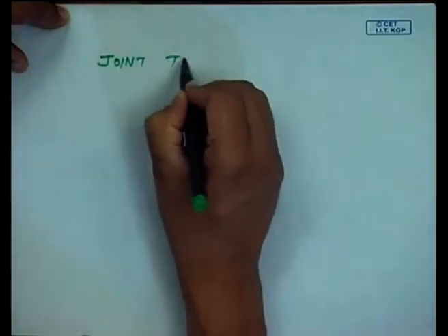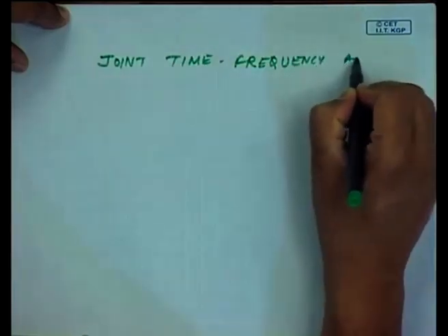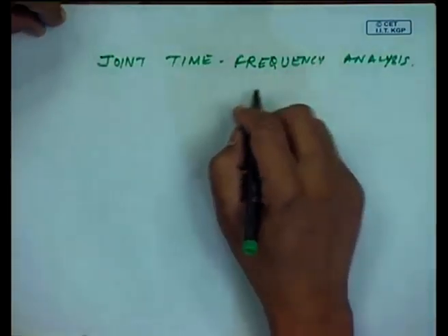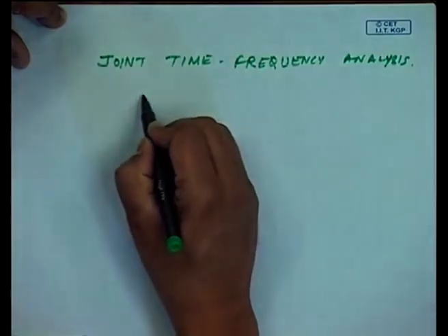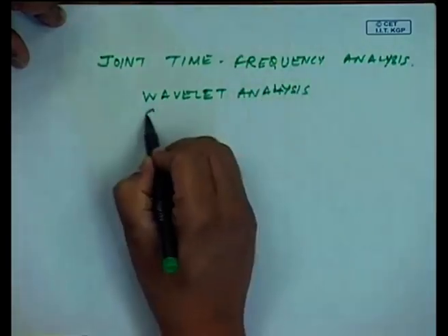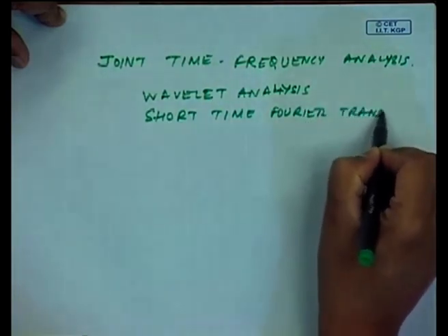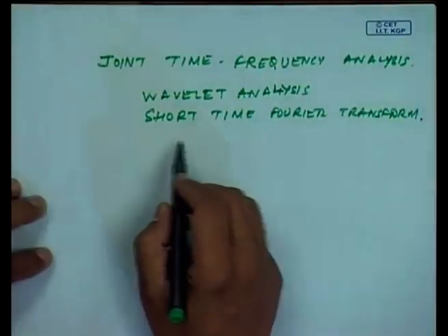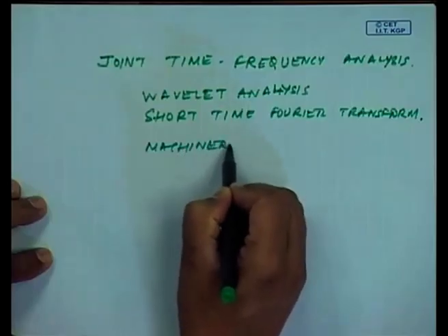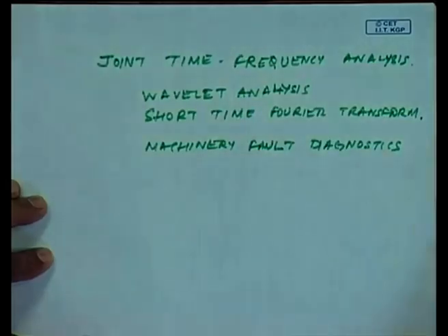But this has given way to nowadays what is known as simultaneous or joint time frequency analysis, and there are few modern methods of signal processing like the wavelet analysis, short time Fourier transform, which has been nowadays used in machinery fault diagnostics, particularly for non stationary signals.